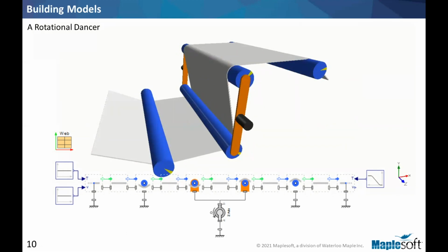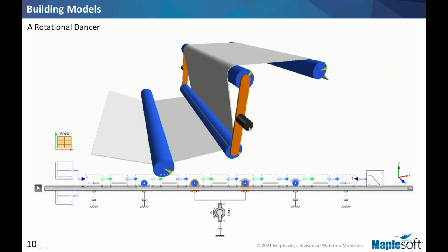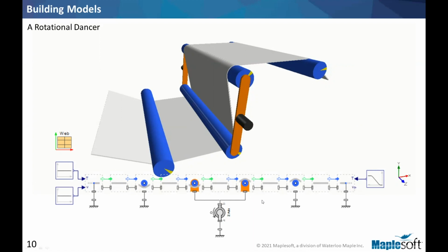So it will resist, and based on the tension and the compliance, one can estimate the tension this way as well, or have a measurement of the angle and use that in a feedback loop. And we will see another example of a dancer and how that information is used in a closed loop control.